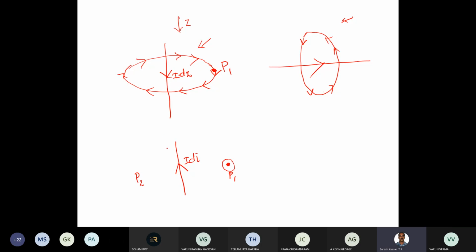In this case, sorry guys, let us assume this is the direction of current flow. The magnetic field lines are perpendicular to the screen, so in the cross section you can represent the perpendicular direction by this shortcut representation. Or sorry, it's not just perpendicular: it is either outward or inward, these are the two possible directions. If it is outward, use the dot and circle. If it is inward, use cross and circle.